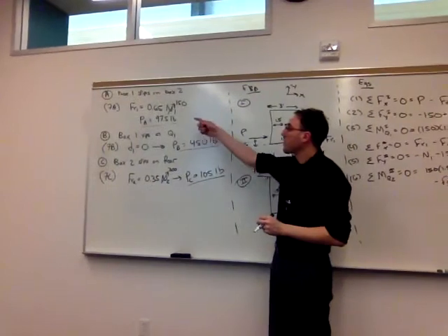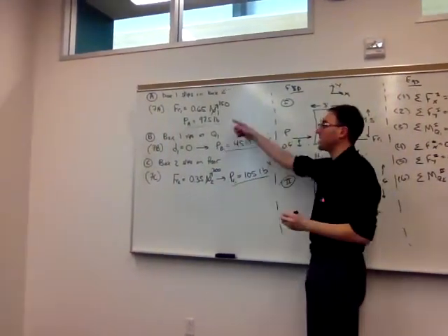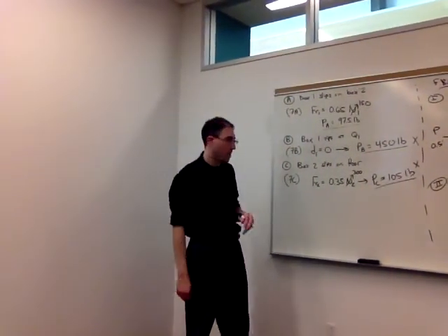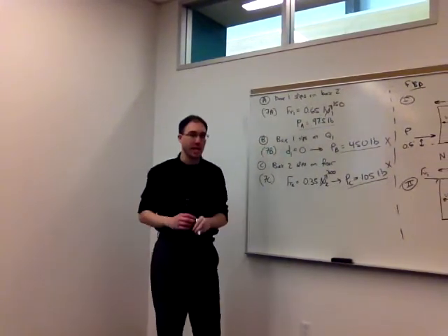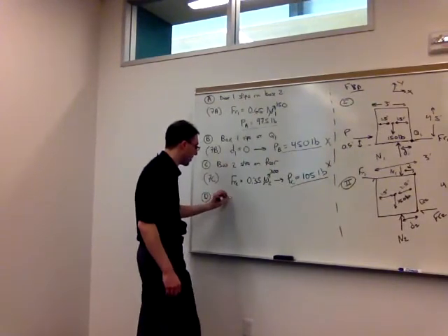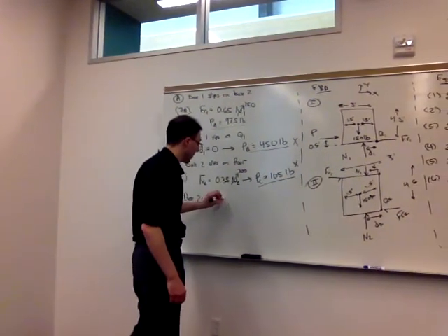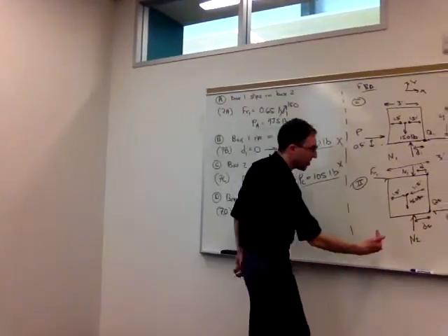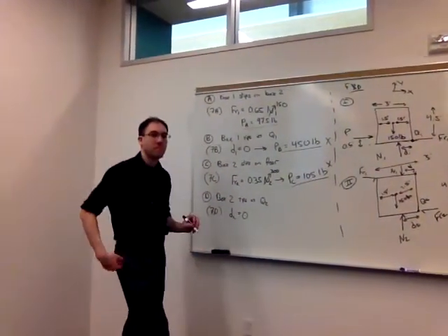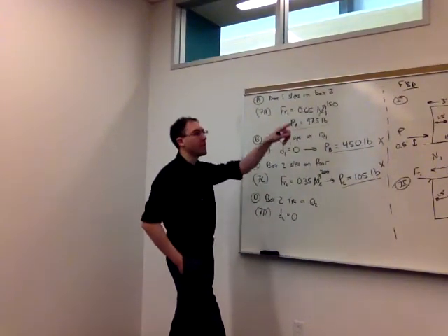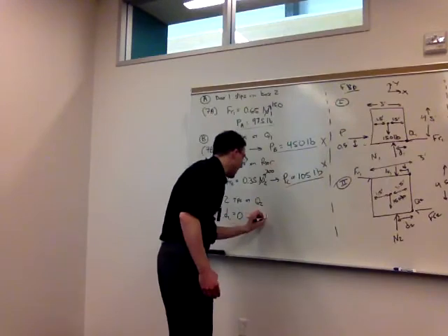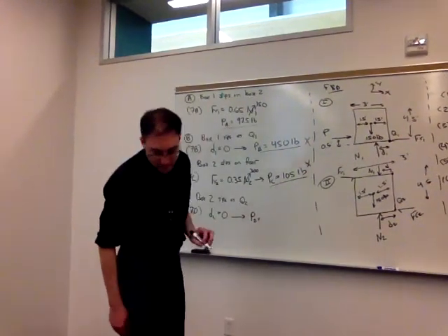We've already eliminated B. Again, compared to A, this can't happen because box 1 would already be sliding on box 2 by the time box 2 would be sliding relative to the floor. So scenario C is not the case either. So finally, the fourth way is we said box 2 tips at its corner, Q2. The normal force N2 is directly under this pivot point, making D2 equal to 0. We now combine equation 7D with 1.1 through 6.1. Specifically 6.1, if D2 is 0, that means that P sub D is 90 pounds.